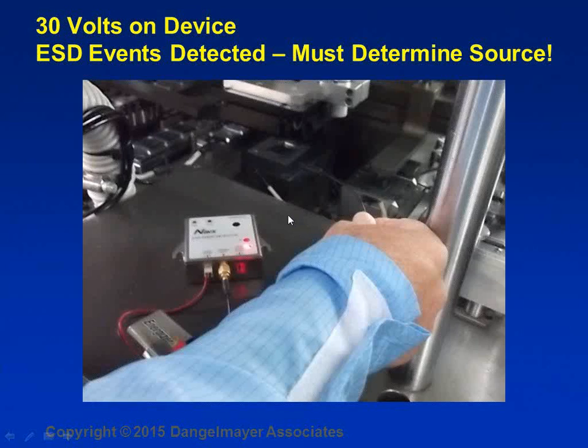So to determine that, we recorded this measurement with a video camera. That enabled us to look at it frame by frame and ultimately determine that there was no risk. The discharge was happening at a moment in time slightly after the device experienced touchdown in this stage in the tool. So we were able to vindicate and certify the tool as safe for 50 volt devices.